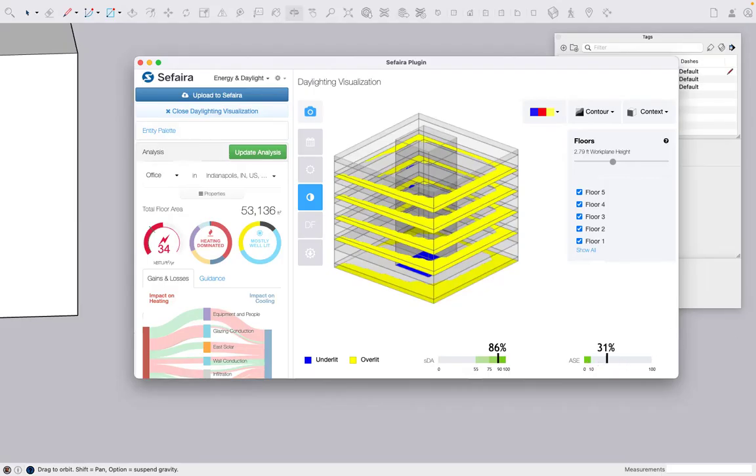You can see with those two metrics, for the annual sunlight exposure here, we're not even close to hitting. I believe these levels here are in accordance with WELL building standard, and LEED as well, kind of common best practice. You're not yet hitting your glare metrics where you want it here, with 10%, and the SDA though is looking fairly well.